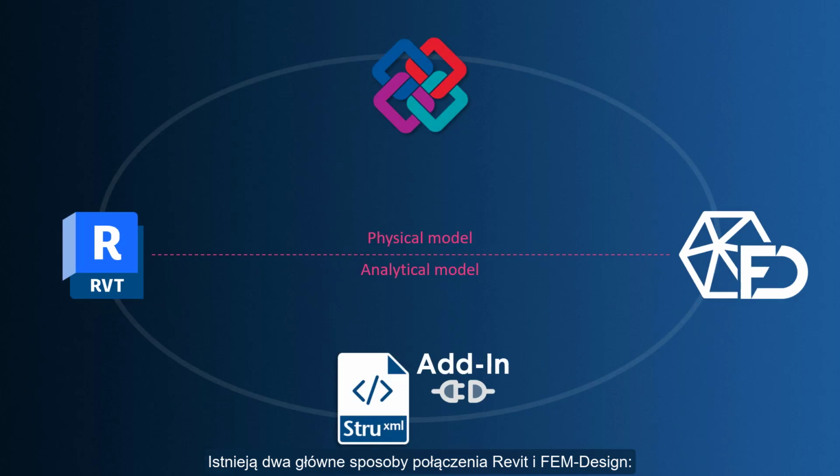There are two main ways to connect Revit and FEM-Design. One is the IFC workflow, where we exchange the physical model through IFC. The other is the direct add-in workflow. It uses the StruSoft Revit add-in and exchanges data through XML, our own data exchange format. Both workflows can go in either direction, from Revit to FEM-Design and back again. But they are not used for the same purpose. The key question is, which connection should be used and when? Let's start with a short overview.